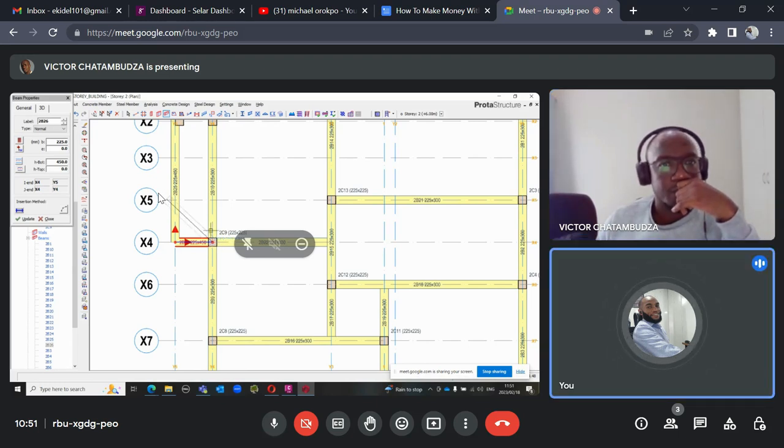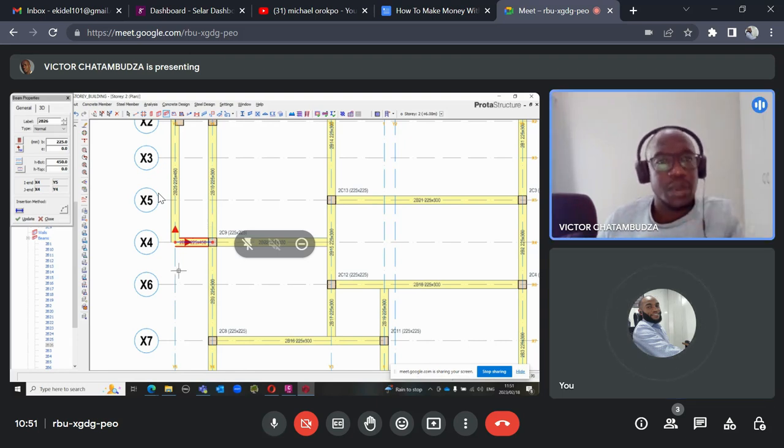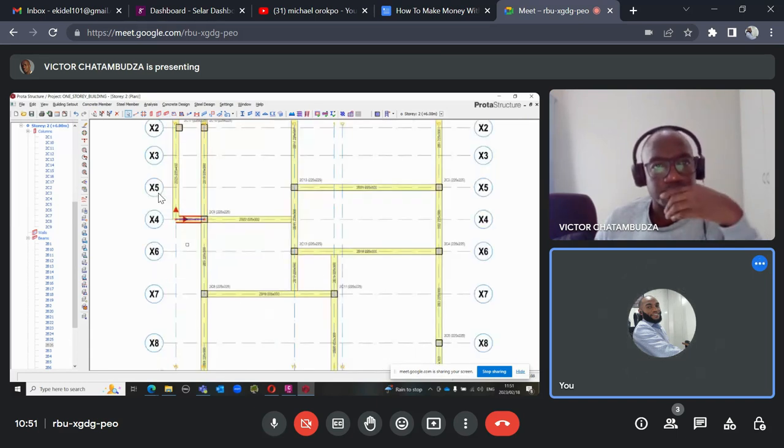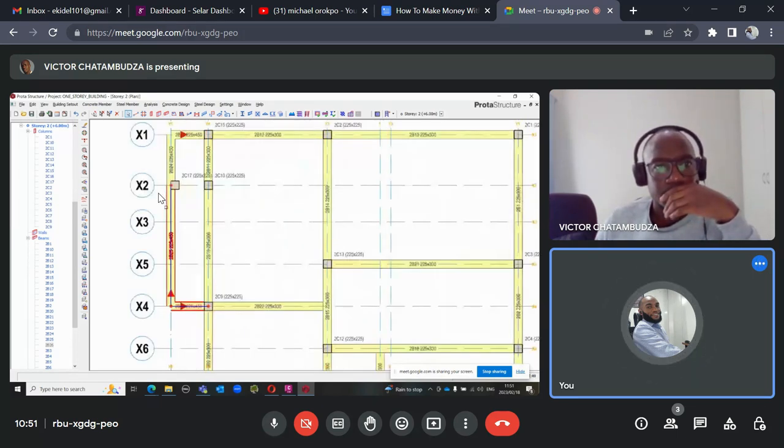Escape first. Escape again. Now click on that beam. Let's now flush it. The vertical beam, yes, that one. Click, right click and say properties.